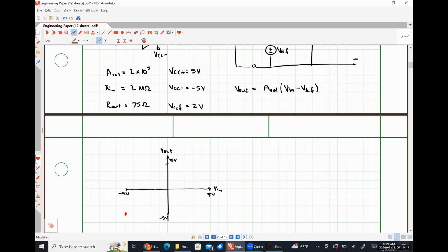Now I think it's going to stay negative for quite some time, so let's evaluate it at Vn equal to 0, with the assumption that if it stays negative, it's not going to just magically change in between because there's no reason for it to do that, right? So if Vn were equal to 0 volts, what would our output voltage be? Still negative 5, right?